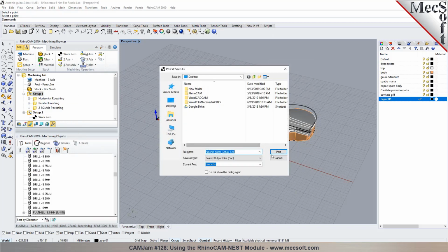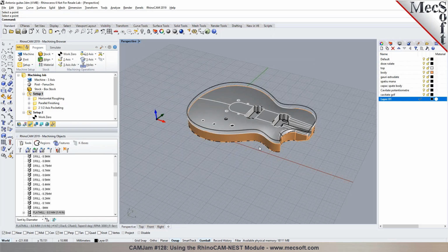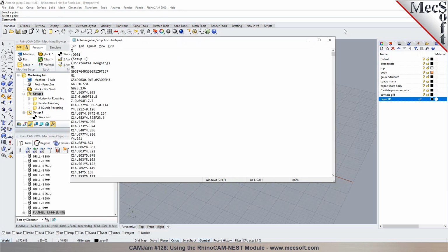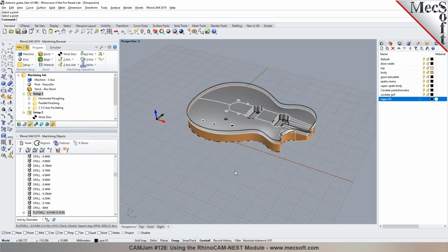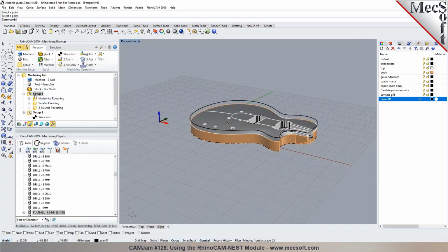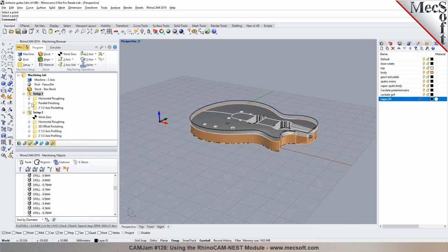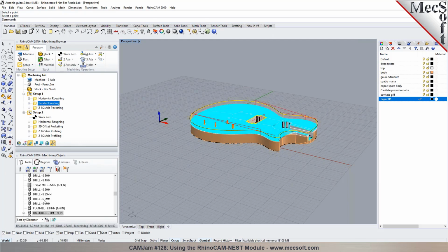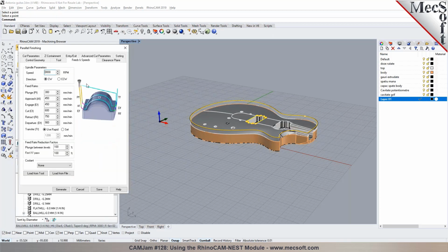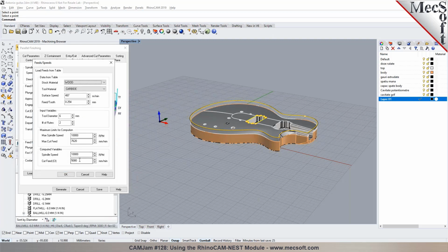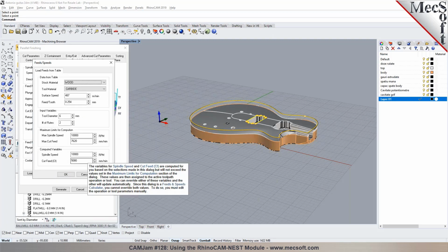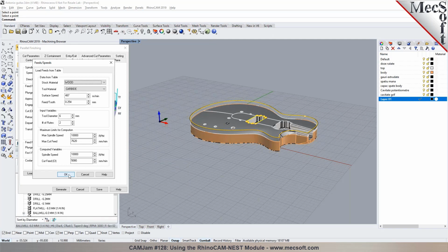And how can I optimize this G code to move faster? You would have to set your feeds and speeds correctly. You can change your settings for the feeds and speeds. So in here, I'm just using the feeds and speeds that were set in the tool. I'm loading it here, but you can always use load from file and define the feeds and speeds based on the material you're cutting. So when I change it, it'll update the feeds and speeds, and then it'll recompute it.